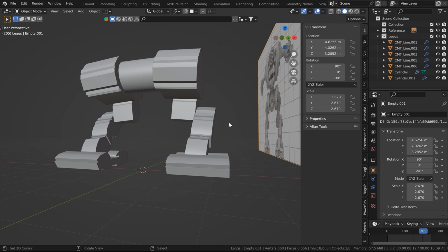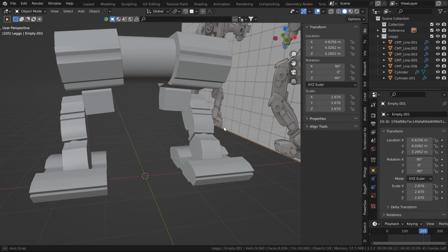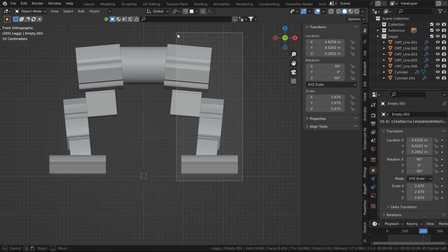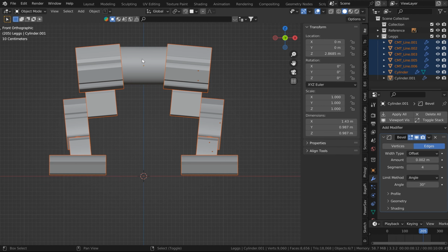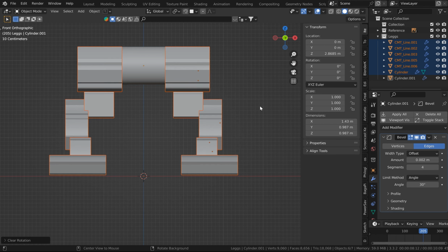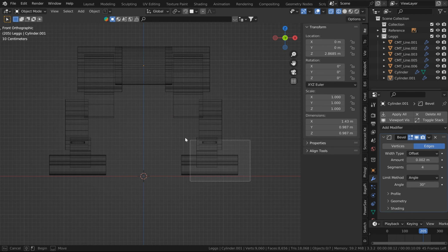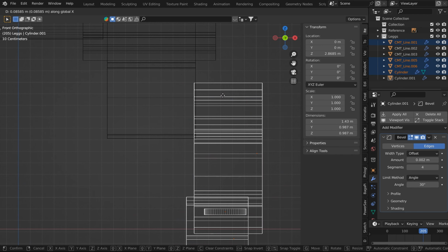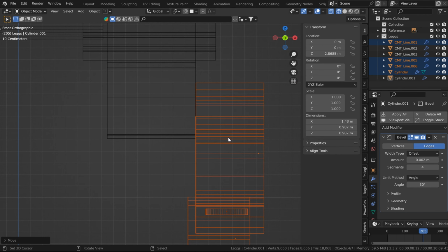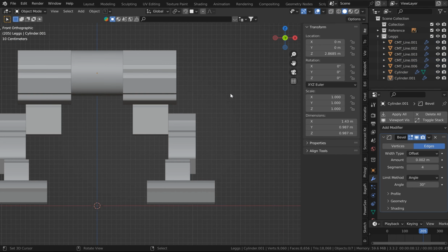So the little trick I just showed you is the one we're going to use. Make sure those booleans aren't there, and just want to grab the leg set here. And if you got the center selected, you can double right click on that. Just get everything selected and hit Alt R, and you will instantly correct that rotation. I'll jump into wireframe so I can select all of this, and I just want to hit G and X, move this over to the side and go back to solid view.